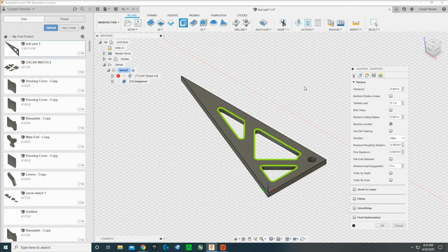It is kind of what it sounds like. The cutting radius of a machine is like the radius of a circle. If it's trying to do an arc, it's the minimal radius of that arc. If you have a really tight minimum cutting radius, the machine can get into smaller corners, and it's going to be doing a lot quicker and finer adjustments.